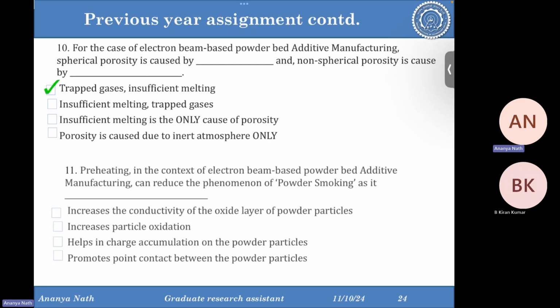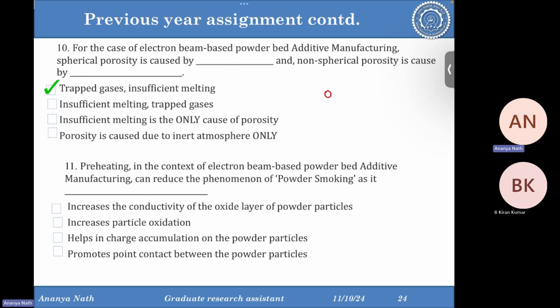So, one picture I will draw. You can see this type of holes in additive manufacturing parts. Holes are small and spherical. So there can be the defect of trapped gas. That can be the defect of keyhole effect also. But if these are like